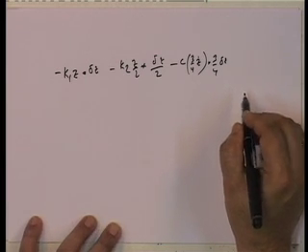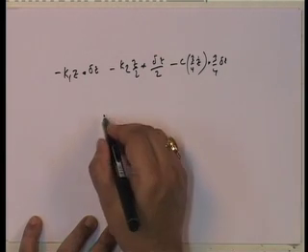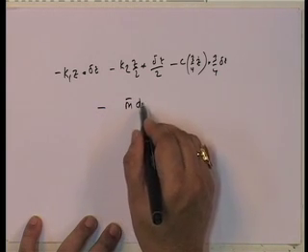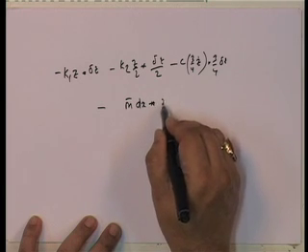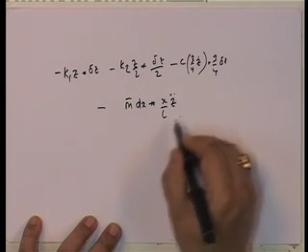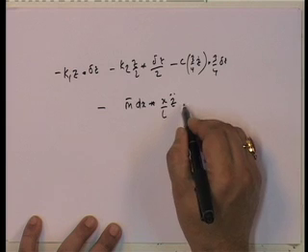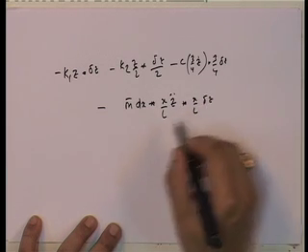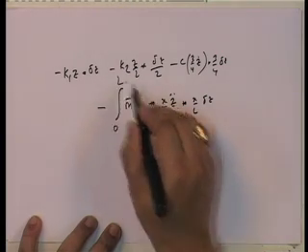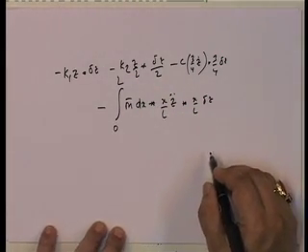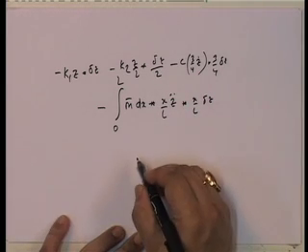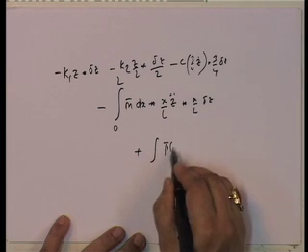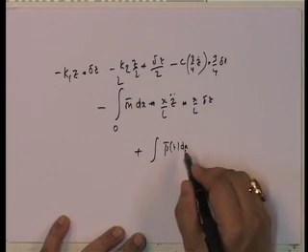Okay. Then what do we have? Then we have minus m bar dx into x by L z double dot. That is the force multiplied by x by L delta z. That is integrated from 0 to L. That gives me the total work done by the inertial forces, and finally, the work done by p bar of t dx.